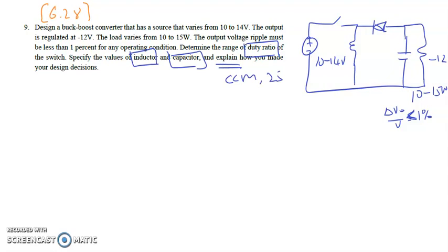We should assume that this system operates under CCM, with the inductor value increased by 25% over our calculated minimum inductor value. The other components are assumed to be ideal. The first thing we need to find out is the duty cycle. We have two conditions here, 10 and 14 volt, and each will have a different duty cycle to respond to the load. So we calculate both conditions.